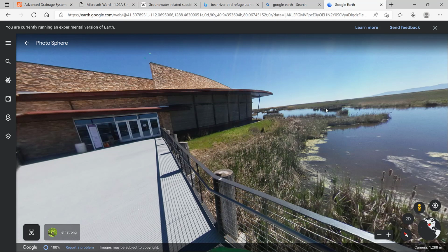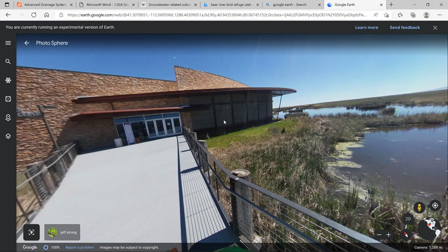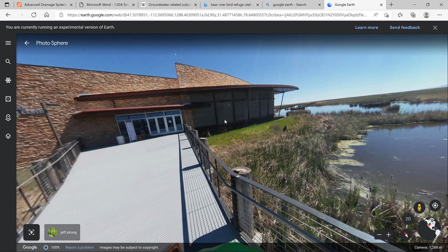The other thing I wanted to share was when we switched off our dewatering system toward the end of the project. Remember, this building doesn't have the trenches down below the building, and the gravel and the piping was all for construction so that we could keep this area dry during construction. It was time to start filling up these ponds, and they wanted that dewatering system off so that the groundwater would come back, and then these ponds would start to fill up. Well, I remember having that switched off, and